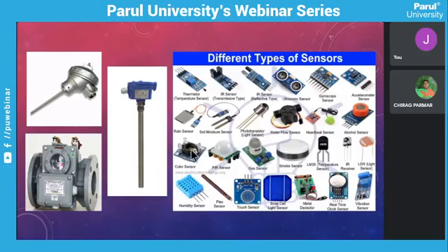A color sensor. It uses a chip used for color sensing. In it there is a chip. A PIR sensor. A PIR sensor has an infrared chip placed inside this bulb. Okay, it detects the heat of the moving object, and whenever it detects something move very quickly, it triggers the output. Okay, the sensitivity of this can be changed with these two knobs. Then there's a gas sensor. Okay, it detects the presence of gas.